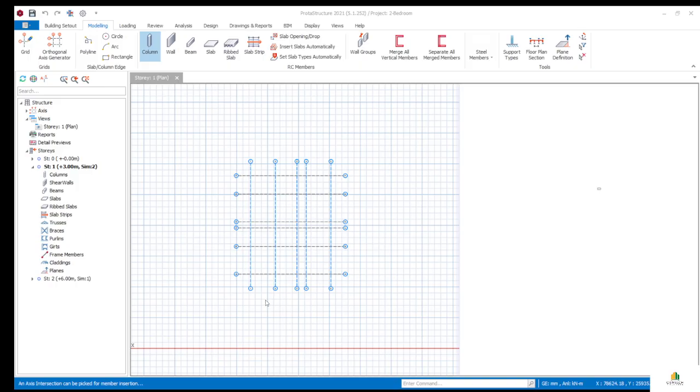Now we don't want to use this, so let's choose the width to be 300 and the depth to be also 300. Sorry. So let's click here. You click where the B is, where the 500 mm is. Click on it to select that 500 mm, then you type 300, enter.